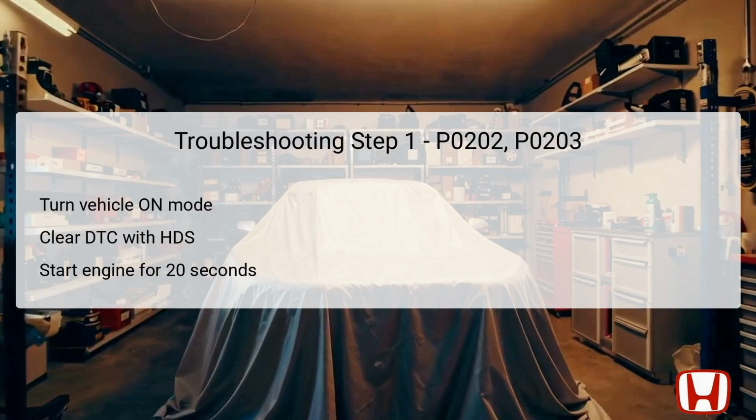For the initial troubleshooting step, first turn the vehicle to the on mode without starting the engine. Utilize the Honda Diagnostic System, HDS, to clear the stored DTCs, which resets the system and allows for accurate assessment of active issues. After clearing, start the engine.